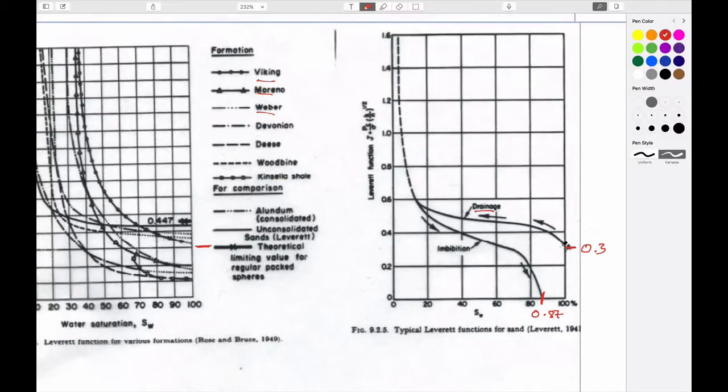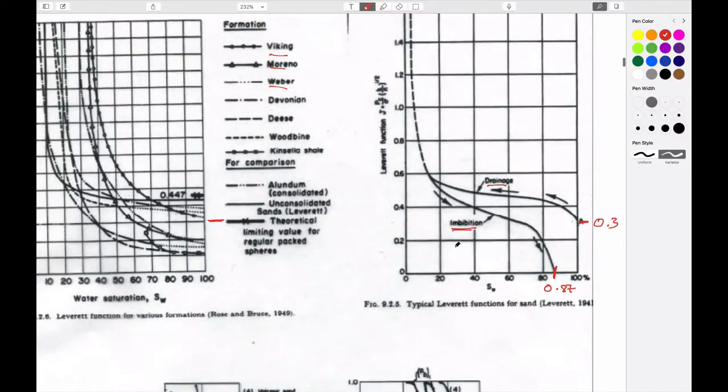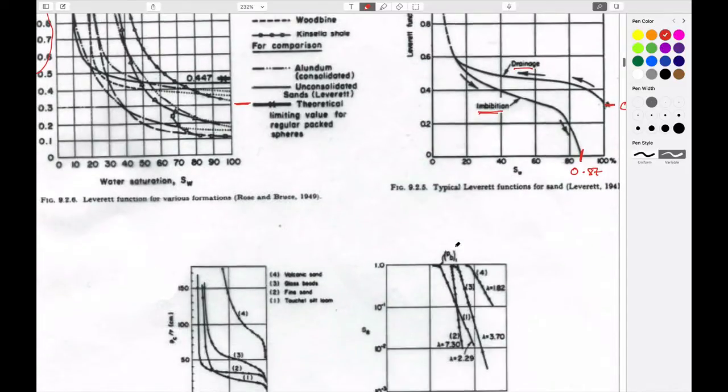In the vadose zone, that other fluid is air that's present above the water table. But regardless, it's drainage of water as you increase the capillary pressure. As you decrease the capillary pressure, you come back here and you imbibe water spontaneously back into it. So the drainage and imbibition is referring to the response to water.